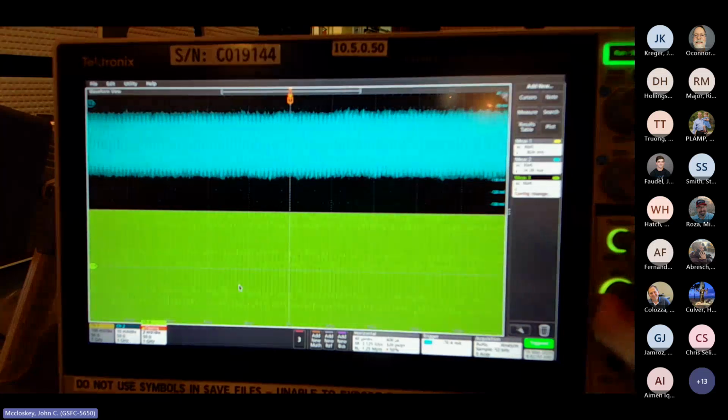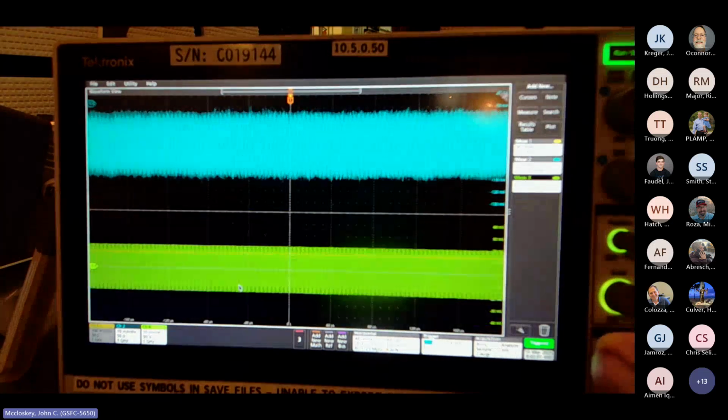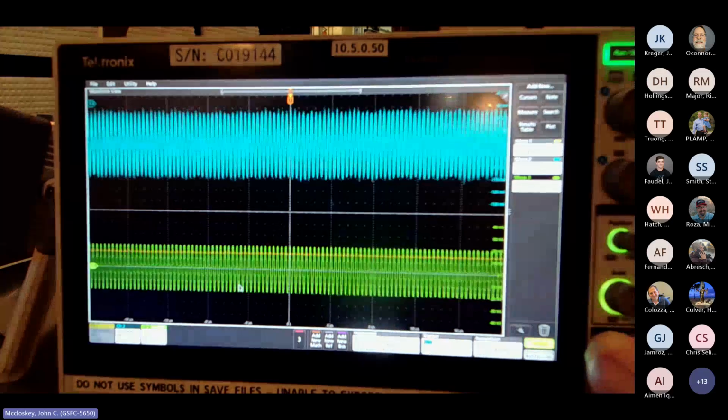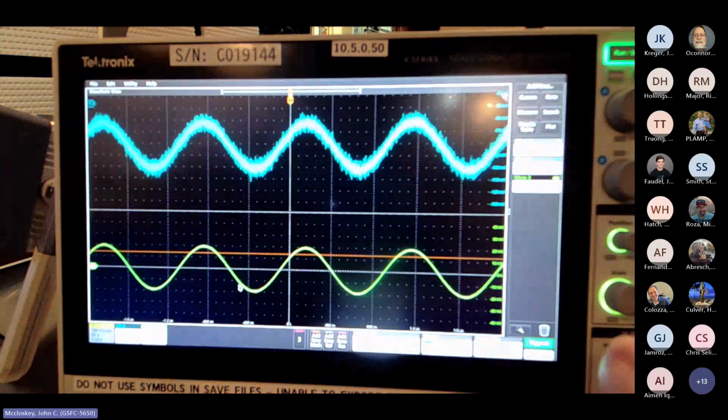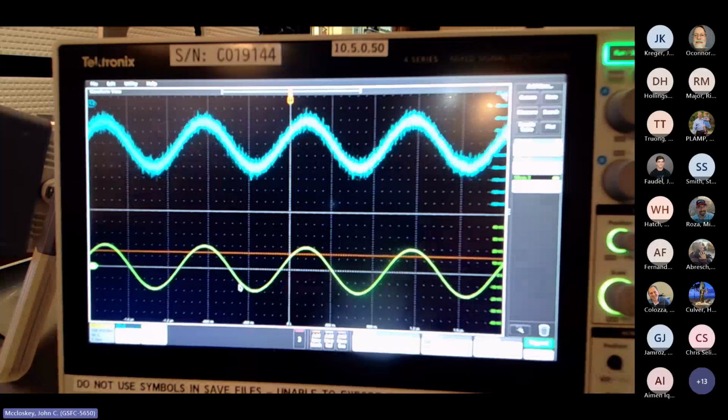All right, we were at 10 kilohertz. We were on the low part of the transfer impedance curve, so it was giving us a low voltage. So okay, up here at 1 megahertz, we're getting a beefier signal. So we're further away from the noise floor.